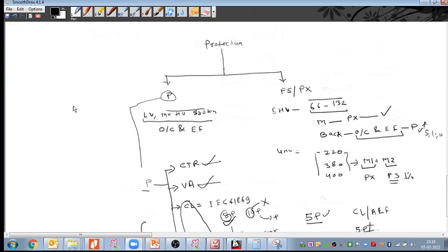For metering cores, it has to saturate quicker, and protection cores should not saturate. So the type of conductor and the physical width of the conductor are different with regard to protection and metering cores. I think the difference in series cores just depends on the conductor.